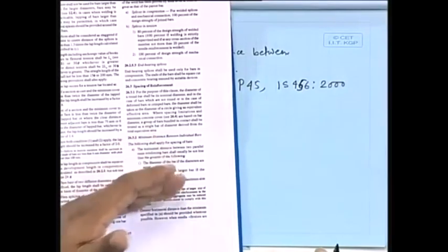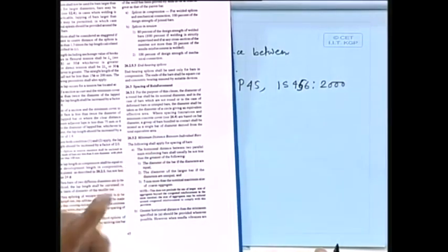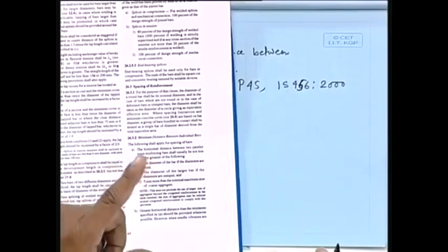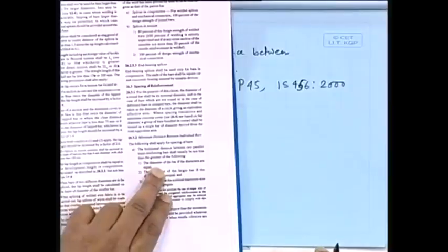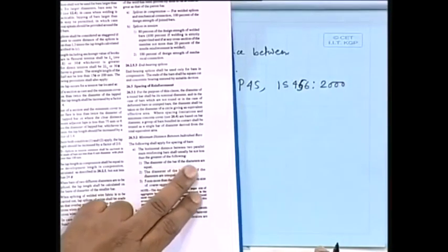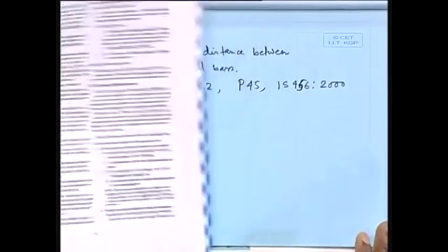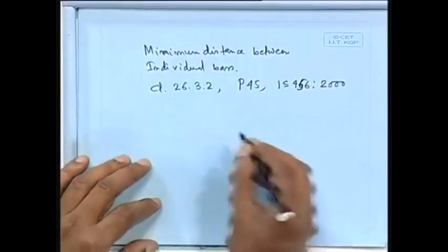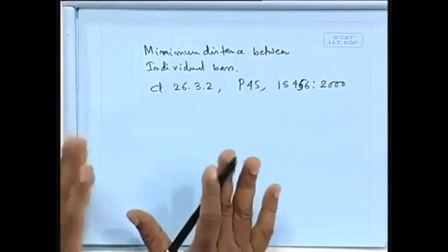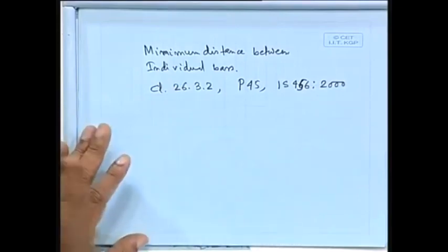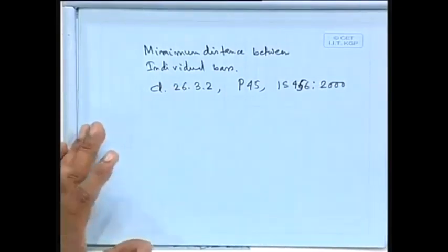So, whatever we shall get, out of that we shall select the maximum one, and that should not be less than that value. So, the diameter of the bar, if the diameters are equal, in this case diameters are equal, which is here say 25 millimeter. Even then our calculation is still wrong, because d dash by d also changed.